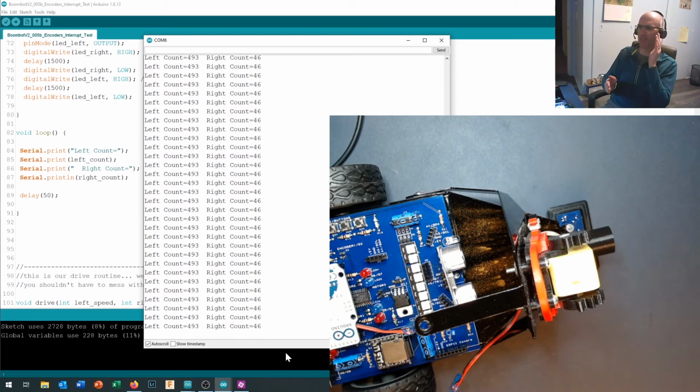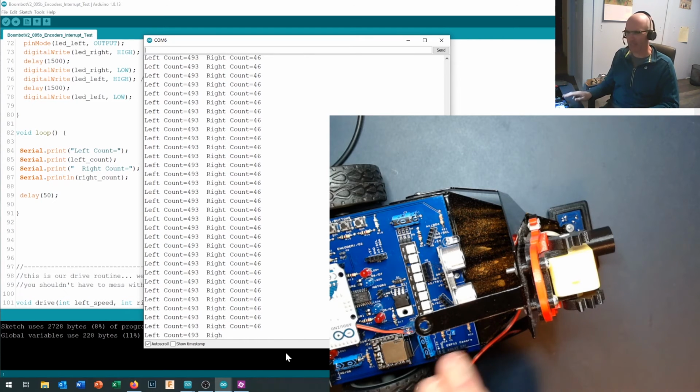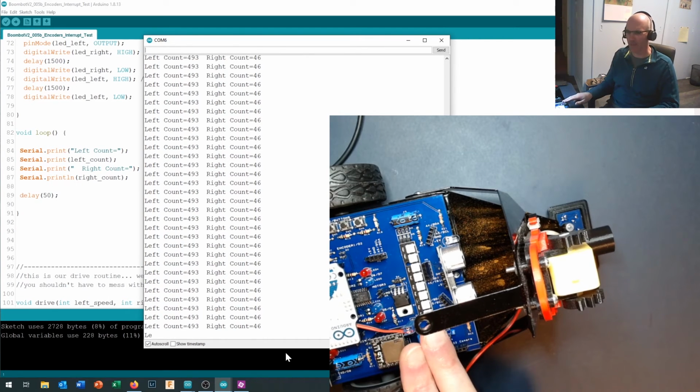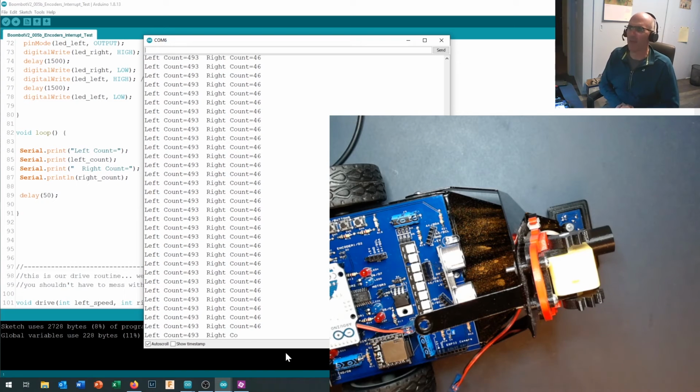And that's one of the advantages of having the slot encoder and the photo interrupter is you're less likely to get that. So there is still a little bit of imperfection in this encoder. If you buy a commercially made encoder, you're not going to run into that problem. So when you're building bigger robots, you're not likely to see that happening again. But anyway, there you go. The encoders are now up and running, and now it's up to you to come up with something intelligent to make your robot go 1 meter.